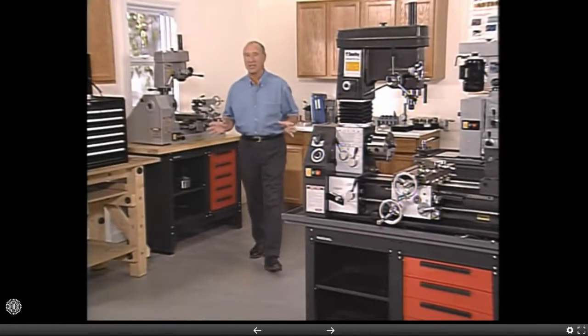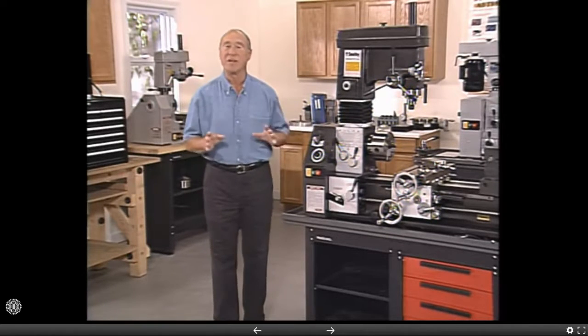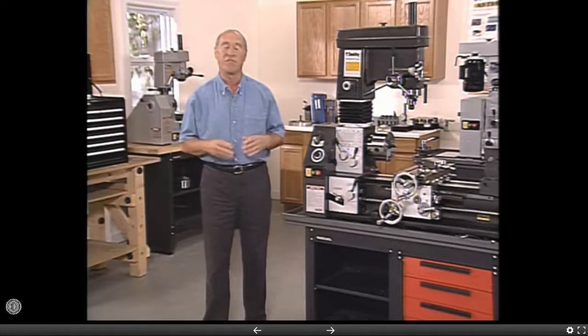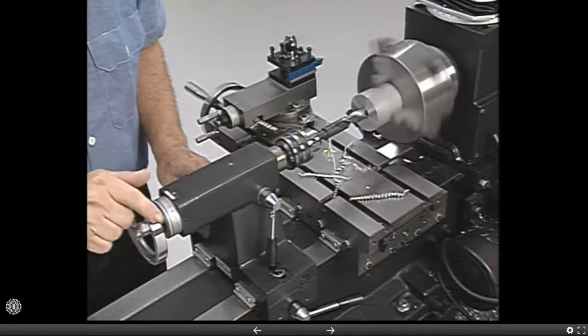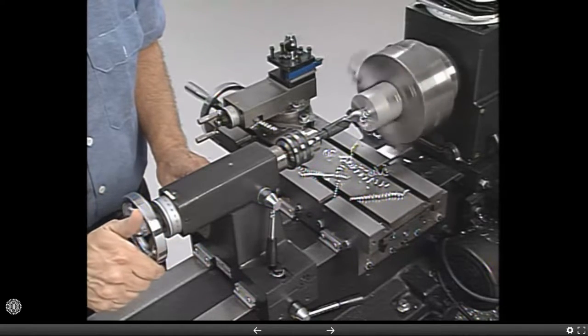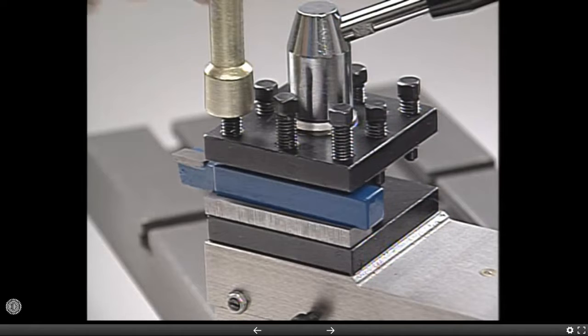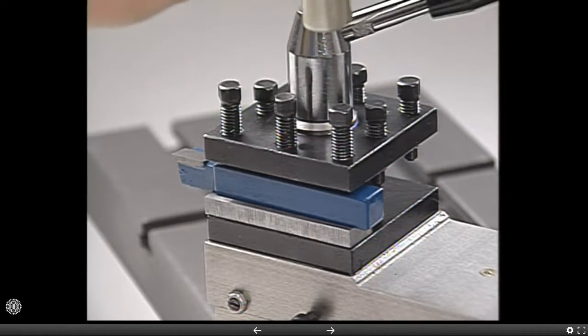There's a wide range of cutting techniques that can be done in a smithy. All of them, no matter how complex, can be done efficiently, as long as you follow a few simple guidelines. The first and most important thing to remember is that the cutting tools, the drills, lathe tool bits, and milling cutters must be sharp. Second, cutting tools must be held securely in the machine's tool holders, free from any vibration.